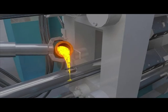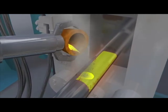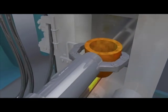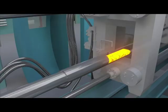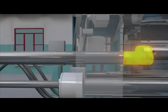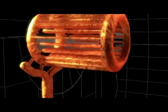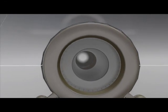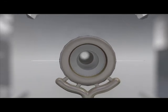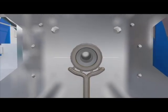Driven by the casting machine, the melted copper liquid flows into the die with a set pressure and speed and passes through rotor laminations to form the rotor bar and front and end rings. After casting, the die is opened and the rotor removed, after which the runner and biscuit are also removed, which completes the casting and production process.